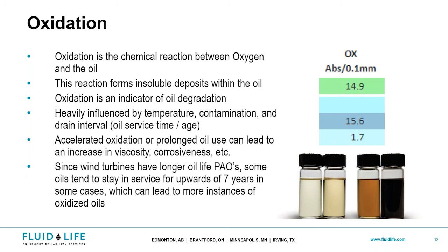And accelerated oxidation or prolonged use can lead to an increase in viscosity, and it could also lead to an increase in acidity or corrosiveness. So it's something to definitely keep an eye on.